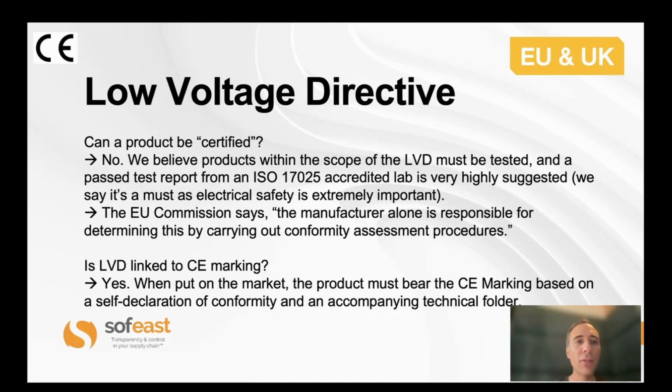Can a product be certified to LVD? No. A test report from an ISO 17025 accredited lab is, of course, very highly suggested. Electrical safety is extremely important. If your product plugs into the wall, that's really not something you should take lightly.